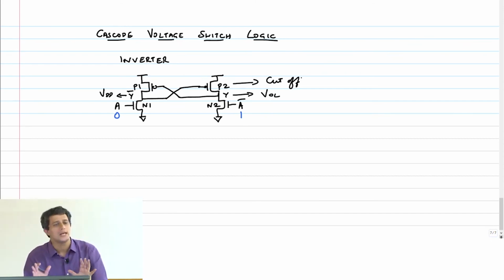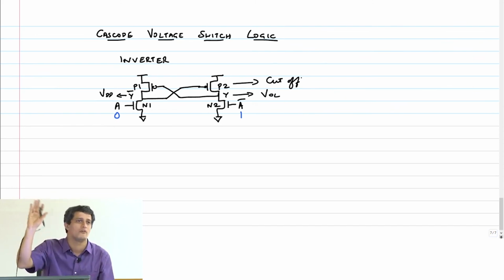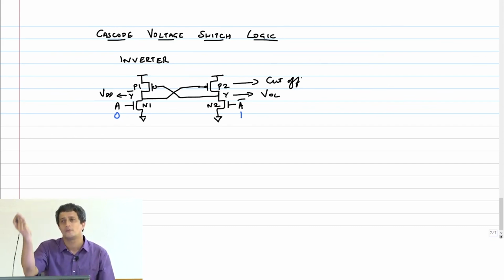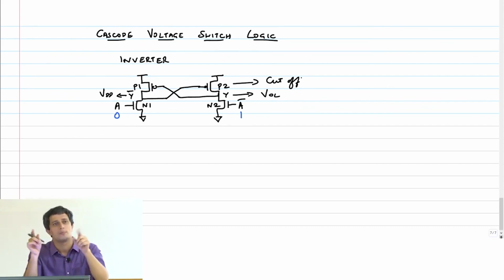So this is clearly a case where it's like a pseudo NMOS transistor, logical effort is low. Note very importantly, my input A or A bar is still connected only to the NMOS transistor. They are not connected to the cross coupled stack anywhere. If it is connected, then the logical effort will go up. That's a problem, right? So this cross coupling is happening only between output and this.